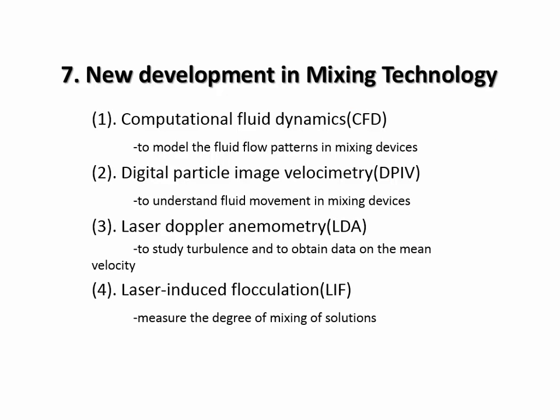And 7 is the newly developed mixing technology: the first one, CFD, to model the fluid flow patterns in mixing devices, and DPIV to understand the fluid movement in mixing devices, LDA to study turbulence and to obtain data on the mean velocity. And the last one, LIF, measures the degree of mixing of solutions. Thank you.